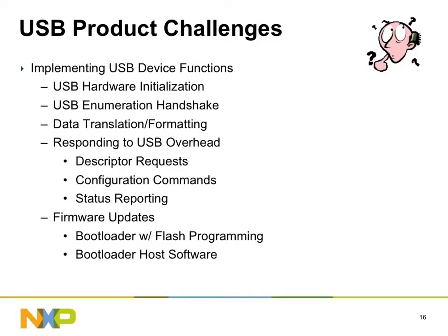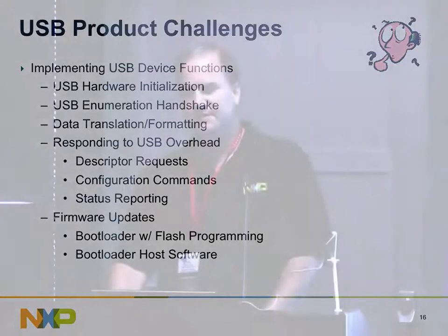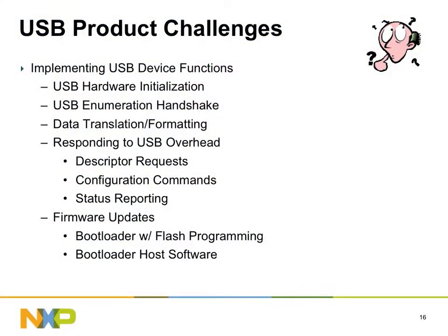So some of the challenges you're faced with when you want to deal with USB: first of all, you have to write the firmware that talks to the USB device. USB is a pretty complicated machine, so this takes a significant amount of work. You have to then debug that firmware, and you have to tune the performance of the firmware. You have to update it in the field once you have it going, which means you've got to write bootloaders and custom programs that people aren't really familiar with.